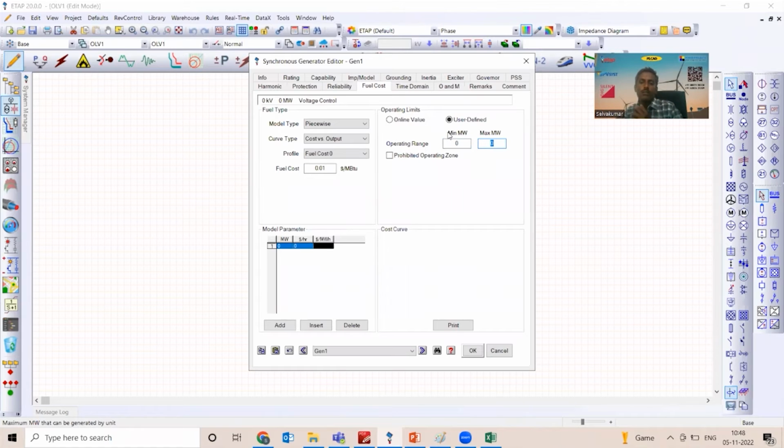Can you say what the typical technical P minimum value is for thermal generators? It is dictated by the mechanical constraints of the turbine, vibrations, maybe white smoke in the case of a diesel generator, etc.